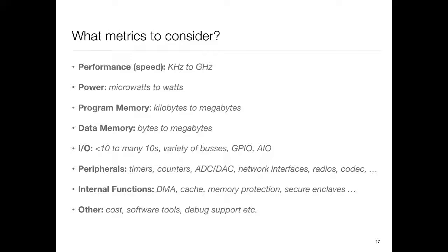I/O. General purpose microprocessors basically provide you an address data bus, and then you put stuff on the board to hook up to it. In the case of MCUs, the buses are inside the processor chip, and what you get outside are GPIO, AIO, and serial buses and all. Okay, there is no address data bus which comes outside.